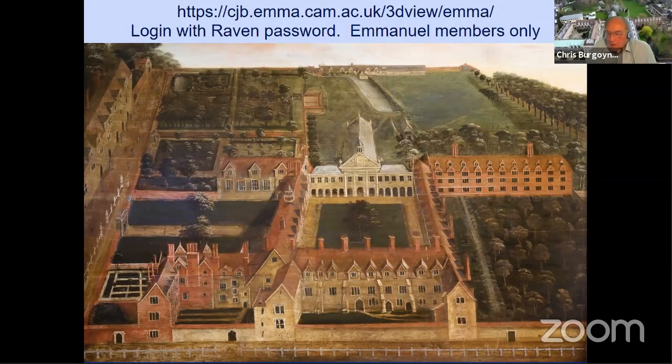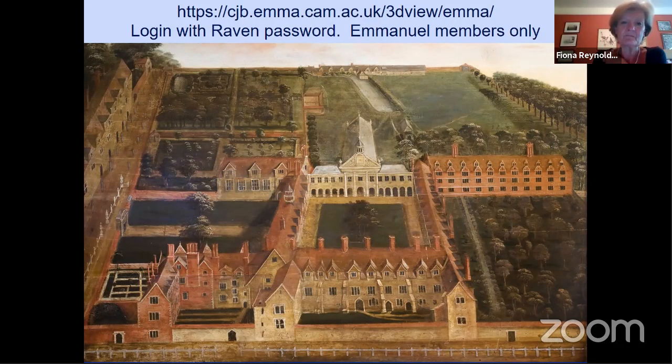And I use the drone for fixing the absolute position of the college relative to the outside world. But the internal positions of different places within the college relative to each other has been entirely generated by the photogrammetry program. So I don't think you have to be accurate with your drone flight. You do need to make sure you look at everything.